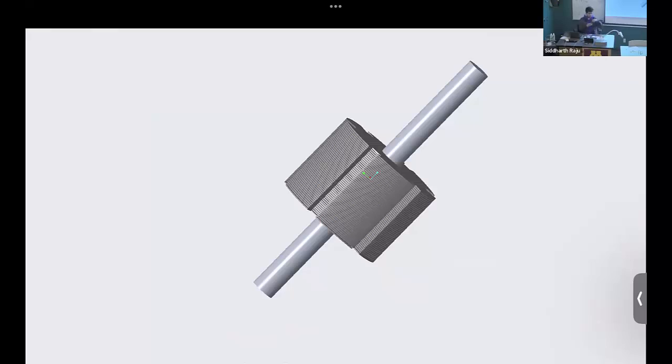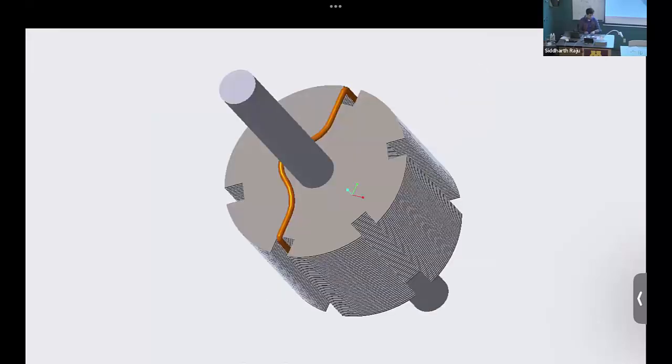So we have these plates stacked up together. We have a rotor bar going right through it. And then the way we wind these conductors is, again, this is not the structure of the rotor I passed around, because that had 12 slots. Here I'm taking for simplicity just 6 slots. And again, there is a skewing in real motors, and in the ideal case, we don't consider skewing.